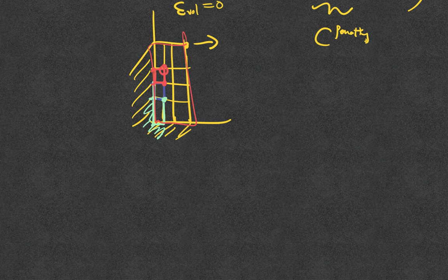So in a theoretical sense, this is just a very soft material where it's really hard to compress it, but very easy to change the shape. But in the finite element mesh, even the shear will be impossible. You see what I mean? Now, what happens if you use a quadratic element?